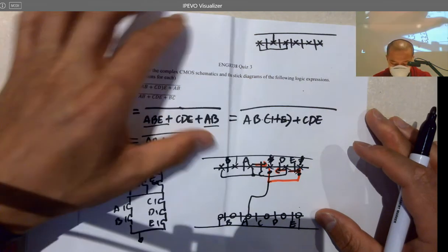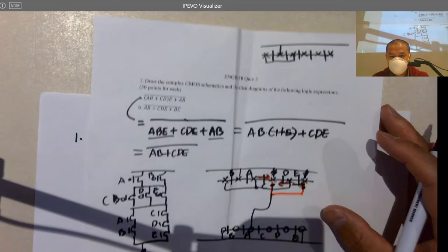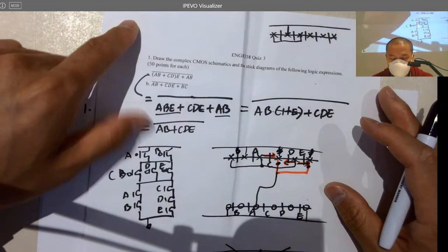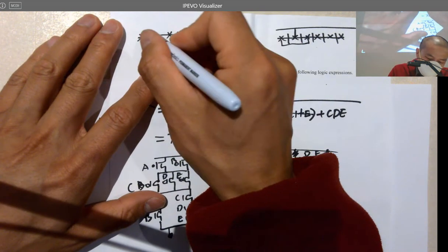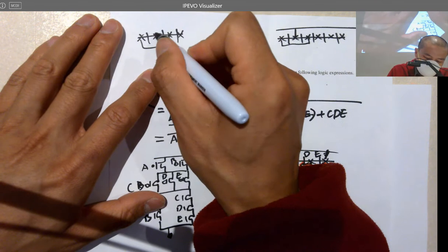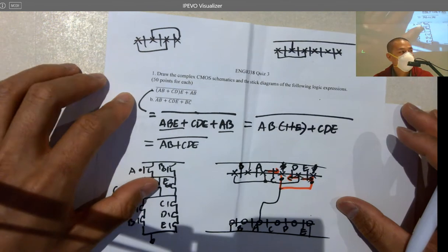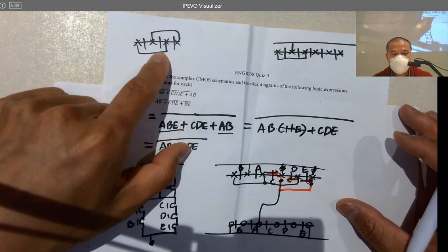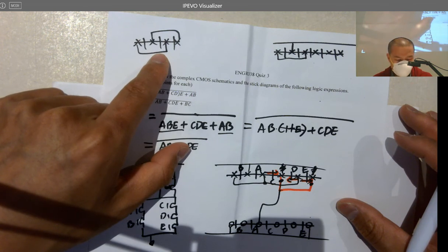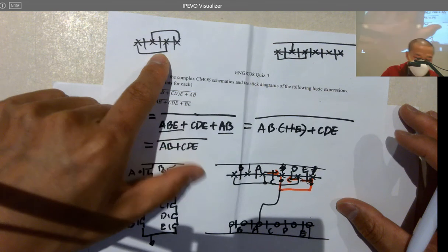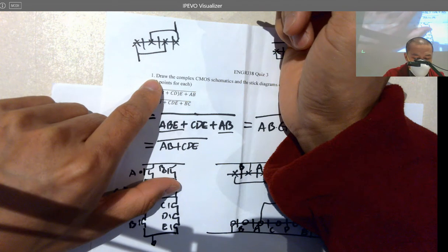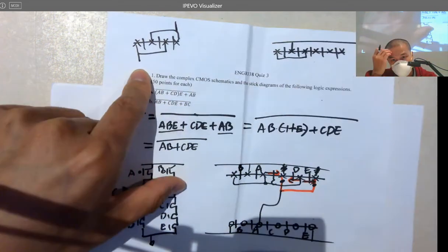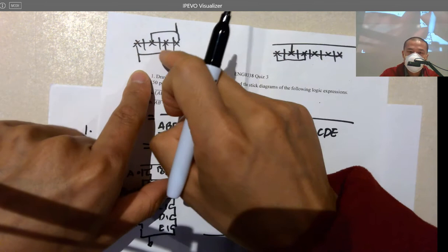How do we do that to get rid of these intersections? So remember the 3 parallel transistors? How do we do that? Like this, right? It's a classic structure. That's how you make 3 parallel transistors. So we can start the trace here and output here, or do it the other way, which will be equivalent. So how can we implement this one in here?